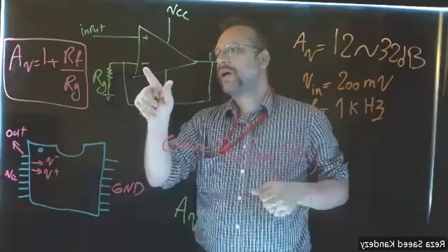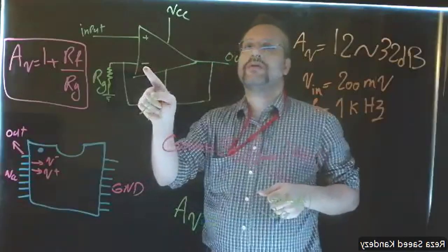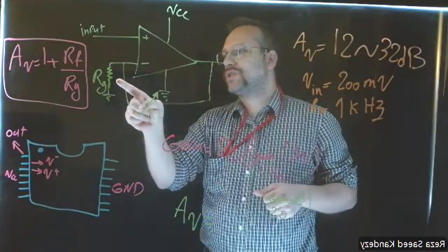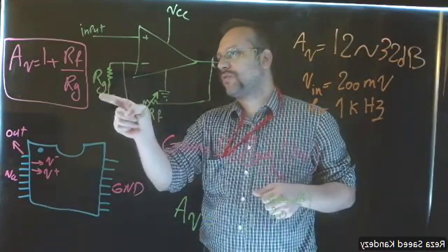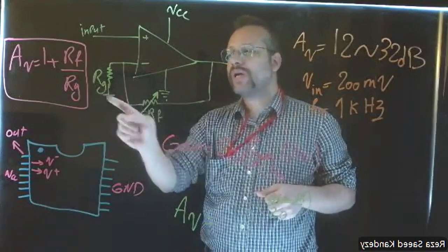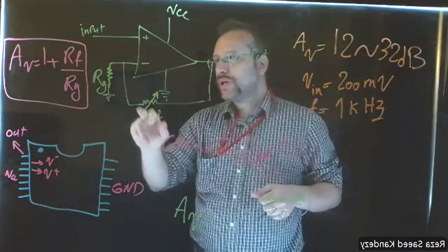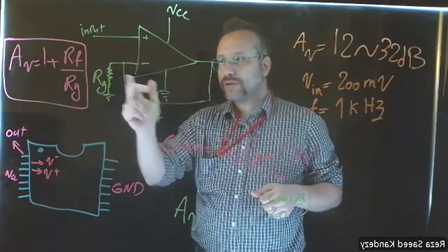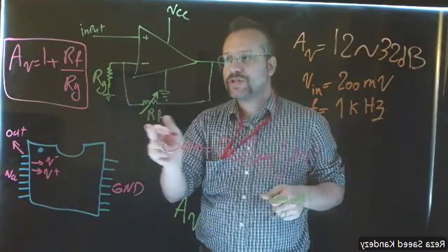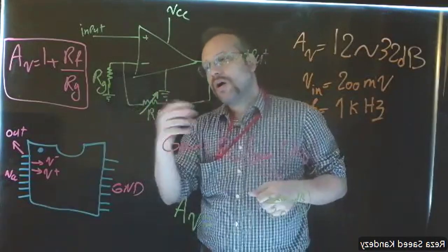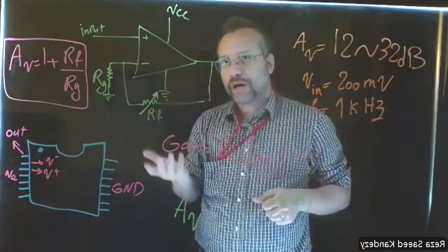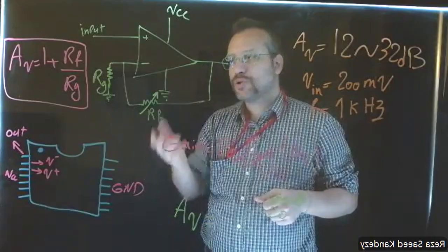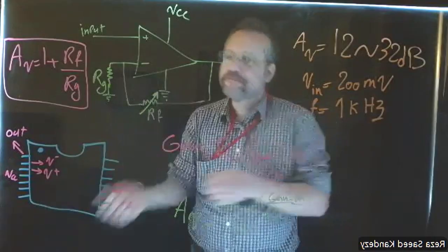We are also going to connect the inverting terminal to the ground using a resistor named the ground resistor, RG. Now, you can use RG as an adjustable resistor, a potentiometer, and have a constant feedback resistance. I'm using this because of my supplies and my inventory in the lab, so this works better for me.